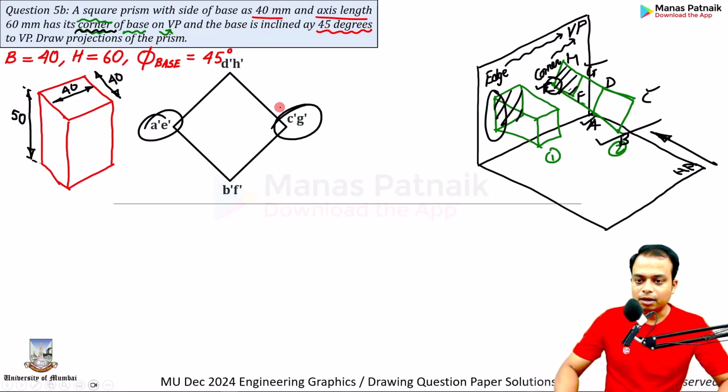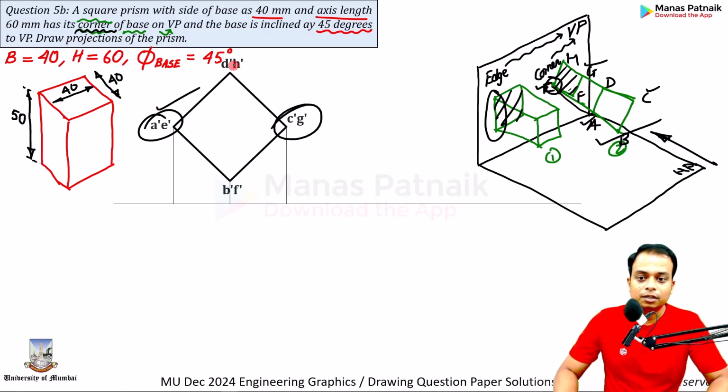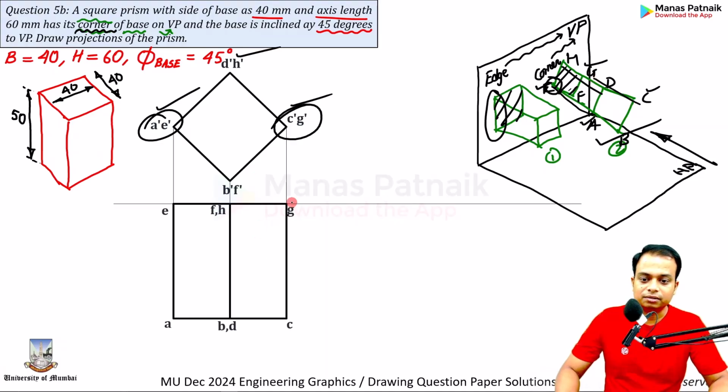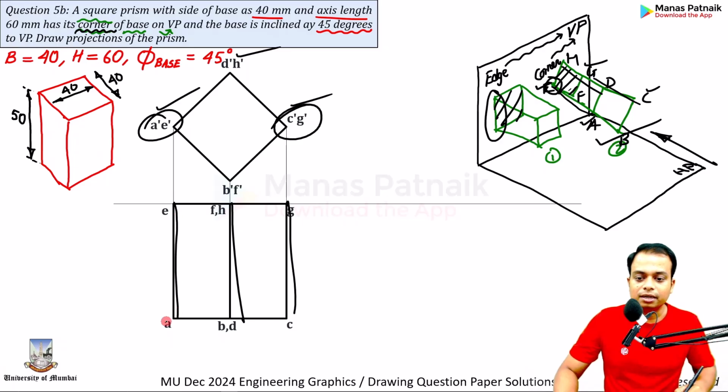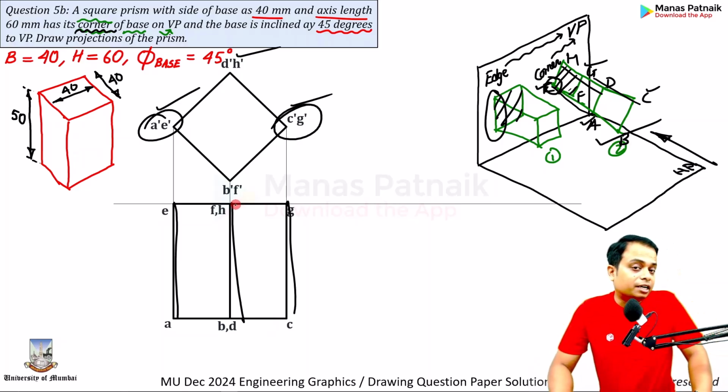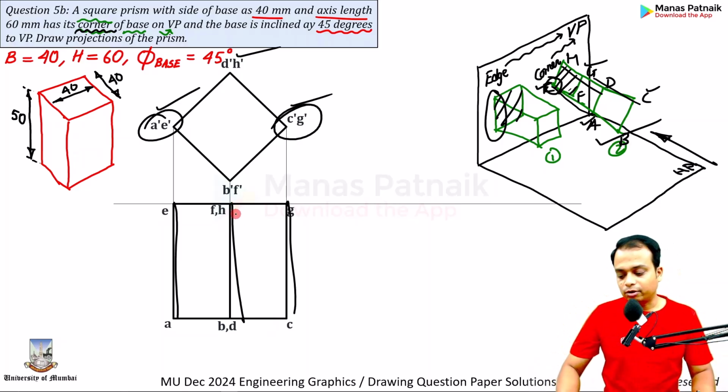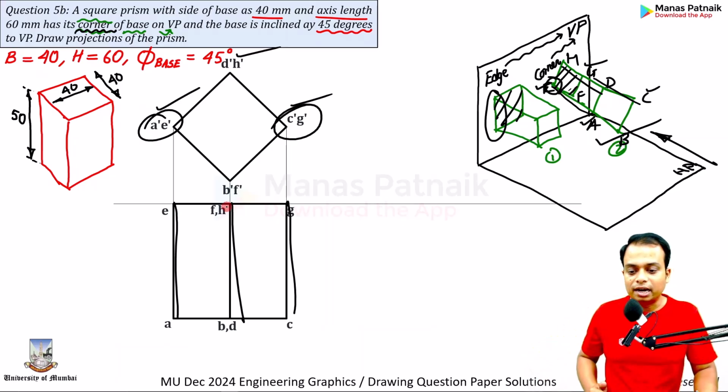Okay. Now, let's take a look at it from the top. How many edges are you going to see? There are 3 edges. AE, DH and CG. HD and GC, in this fashion. GC, DH, EA. This BF over here. Well, it can't be seen, but it can't be represented by a hidden line or a dashed line either. The reason being very simple, because it is being overlapped by a solid line above it.